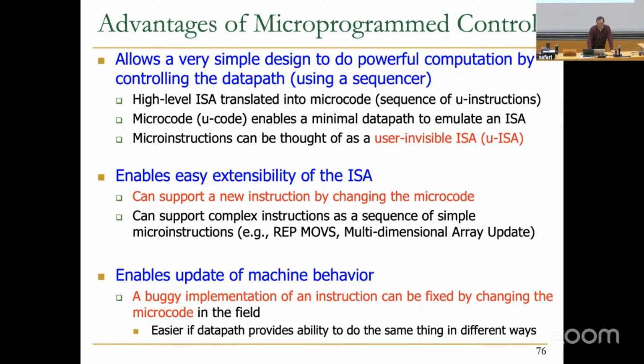Okay, so now I've kind of covered the microprogram control relatively quickly, but this is really just for your benefit because I think it's a very nice and clean way of designing a system. You have a clean microcode and you can update it even after the processor is in the field, right? You can patch the microcode basically. So now you know what it means when, for example, a major company releases a microcode patch. What they're doing is they're really updating the micro instructions in that control store table, meaning they're updating how they process an instruction using these control signals, right?